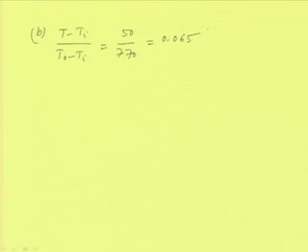again we have (T minus T i) by (T naught minus T i), and that is equal to 50 by 770. The negatives are cancelling each other, and this becomes 0.065, and that is equal to 1 minus erf of x by 2 root over of alpha t. Now, what do we have to find out? We have to find out the value of time t, and x is known, 0.01. So, from there we can find out that x by